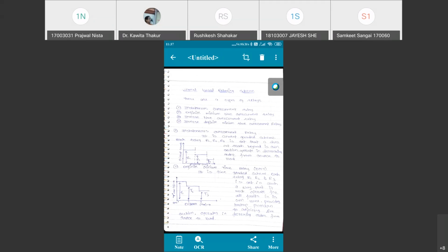The solution of this problem is to use an instantaneous high set unit along with the definite time relay. And the application of DMT is mainly this scheme. This scheme is suitable for systems where the impedance between the substations is greater than the source impedance ZS.